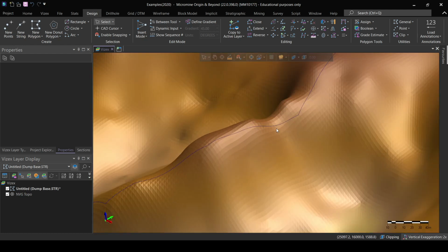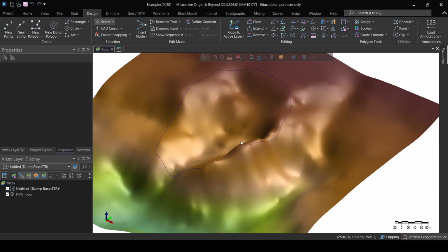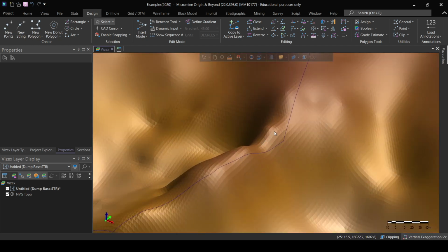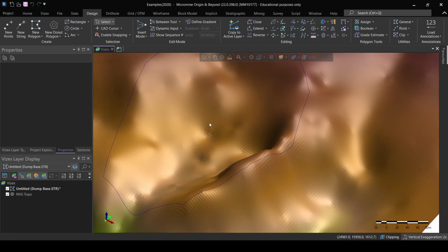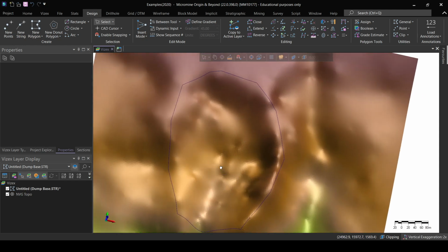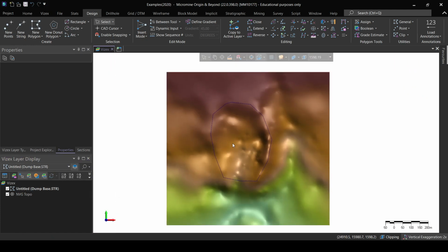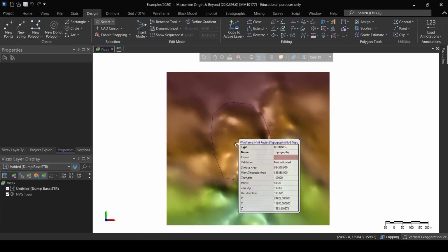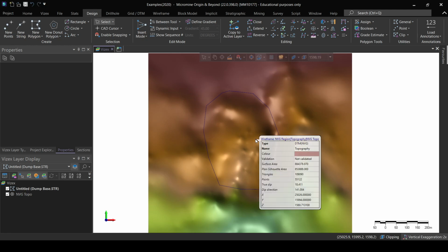Now this might not be very practical, so you cannot have the waste dump have a slope in here, because that's 100% going to cause a slope failure. So make sure to choose this in a better way, because I'm doing this roughly to show you how you can do this. Now I'm going to save this one. Now I can start to play around and see how I can make the dump design fit inside this area, and it's going to be a lot of iterations.